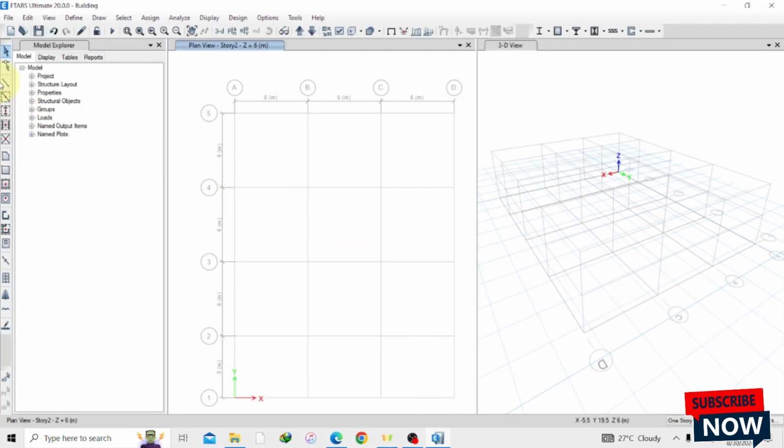So looking at this, we have various tools here. We have our beam, our column, our slab, and our walls. So we also have to learn how to do that. So first of all, we are going to start off with the columns. So looking at here, we have 1 story. When we are about to place our columns, we have to change this to all stories. That means whatever happens at the first or the upper story, or whichever story you do the editing on, the same applies for the various stories. So let's select all stories, and we are going to place our column here.